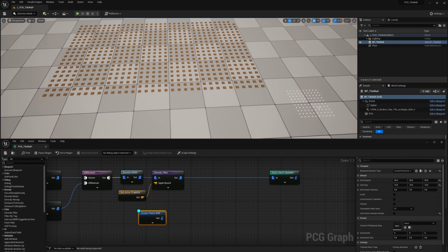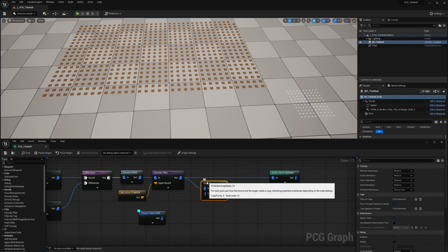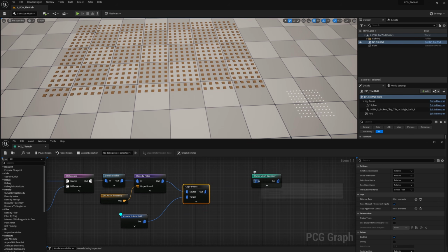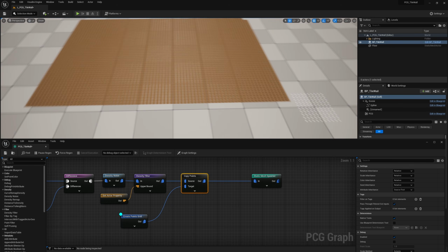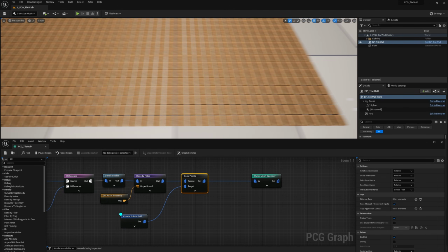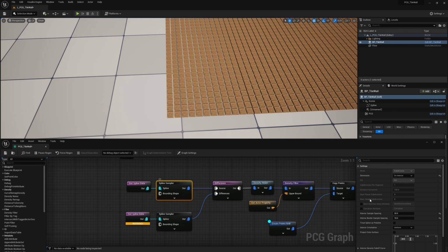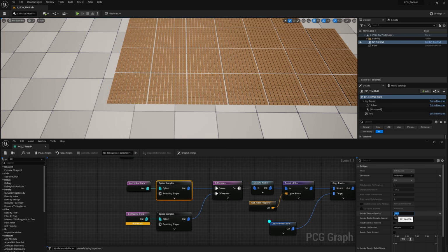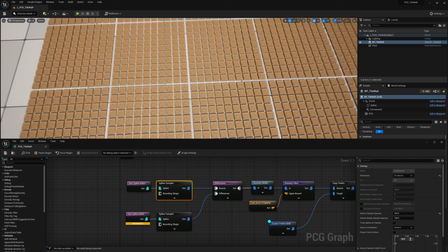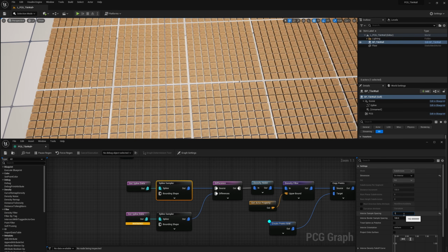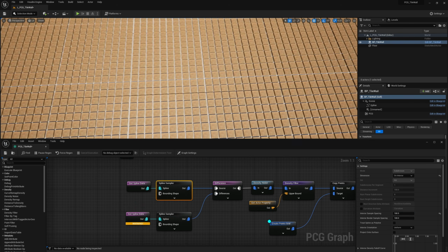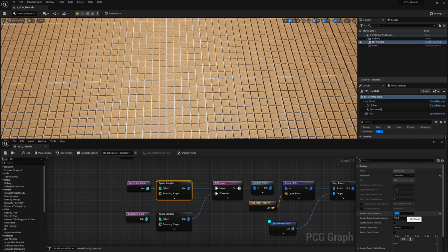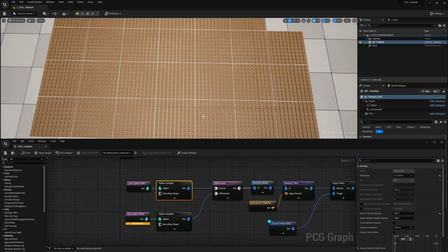That seems pretty good. So now we want to get these points in here. So for that, we're going to go ahead and copy points. The source is going to be our original points, and the grid is going to be the target. So if I unhook this and plug this in, we now have a lot of overlapping points here. So we've got to adjust some values. So in here, instead of 20, 100. If I go 105, you can see there's a gap. 102, still a gap. And you might want a gap in between them, a little bit of extra. So in fact, let's go like 100.5, so we get a little gap in between them, or maybe 101. So we have a little bit of a gap in between the large tiles, so we can really tell them apart.